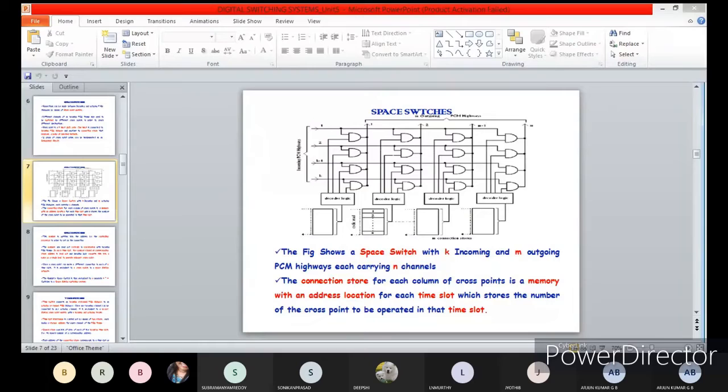See, there is a local exchange. If you want to connect any tandem or route switch in a particular local location, it must be able to connect any channel of one of the incoming PCM highways to any channel of the outgoing PCM highway. A connection occupying different time slots of incoming and outgoing highways is called switching. Don't confuse a highway with a group of incoming lines or a group of outgoing lines.